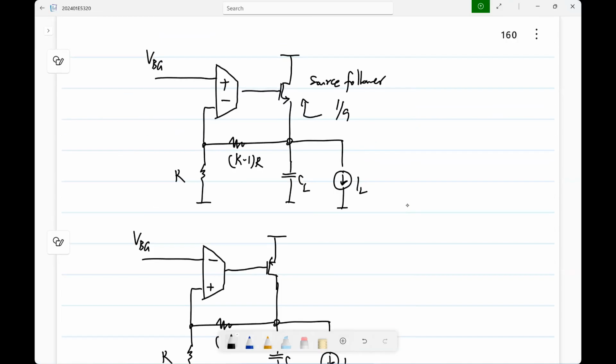So that means that this resistance is already low, and when you put it in closed loop, it will become very low. It will be reduced by the loop gain. Okay. So this can give you much lower DC output resistance, because after all, you want to make a voltage supply, that is a voltage source, right? Something that mimics a voltage source. So that means that your output resistance should be very low. So this will do that.